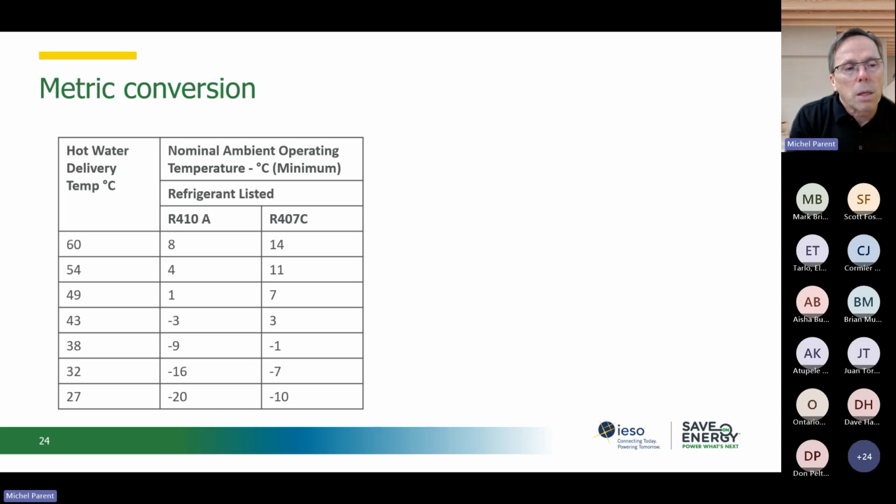Used straight, as we saw, it has temperature limitation. So that's also a rule that you have to keep in mind before you start thinking of heat pumps. We talked about the rates when we're looking at the different types of heat pumps. Always remember, what is the temperature level? A heat pump is not about energy. A heat pump can provide a lot of energy. The problem is the temperature level that you will need. So you need to know your loop requirement.